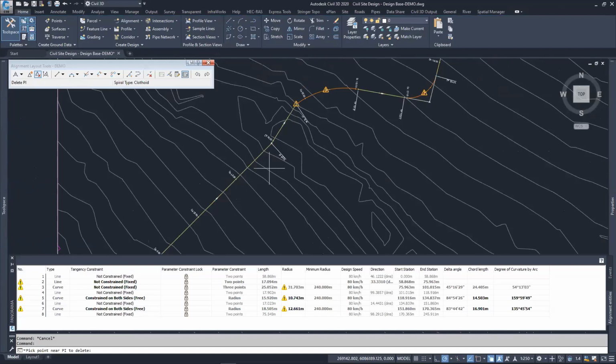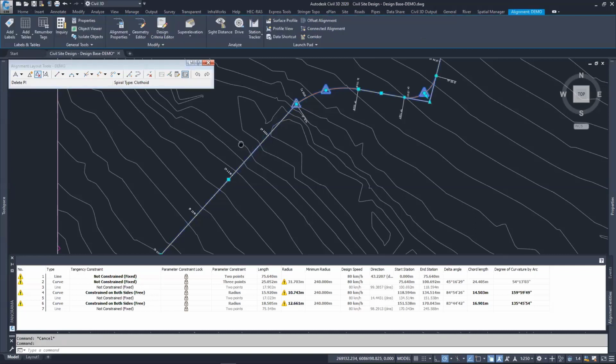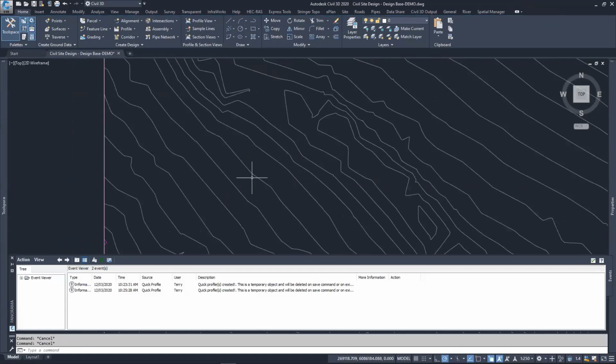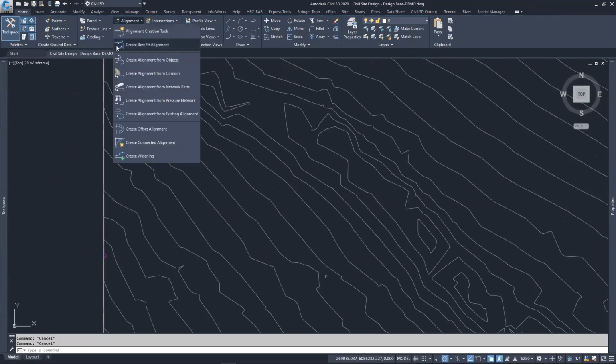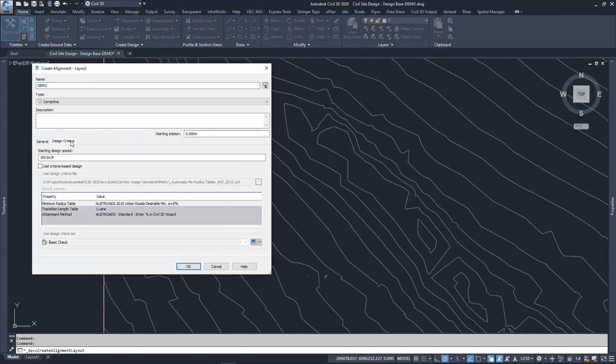Okay, same as before, we can just delete IPs. I'll just make this one fresh. So that's the automated method where you can just go tangent to curve. Other methods, and we can close that. Other methods using the civil site design tools entirely. This one demo again. Centerline, set design criteria, same as before. Change that to 50 k's an hour.